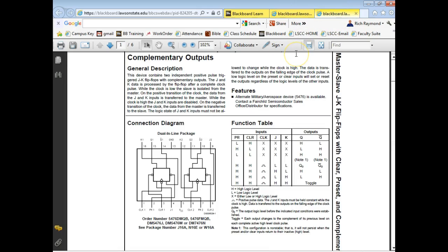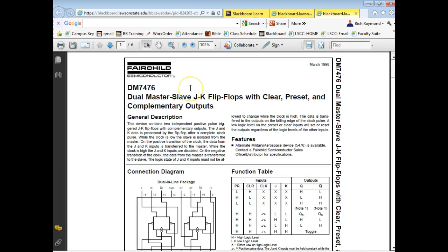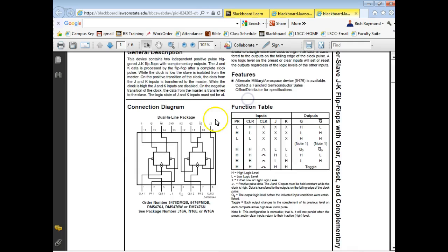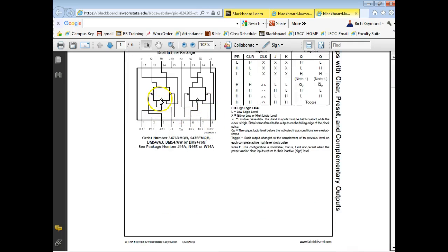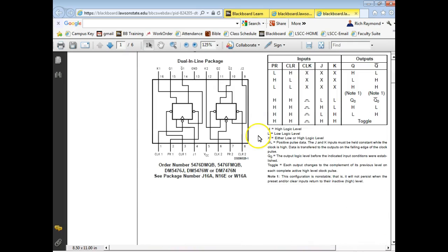But when we bring up a 7476, which we'll get into later, this is flip-flops, and that was one of our lectures. This is a JK flip-flop. All of a sudden we pick up another little symbol right here. Can y'all see that? So what it is, this pin right here has got a triangle on it, and then it's got a bubble. And it's not labeled enable anymore, it's labeled clock.